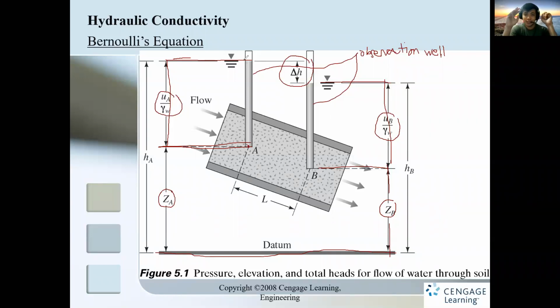That is one example of head added. If the pressure of the water is not enough to reach your tanks, that's the time you will need to add a pump, so that the water shoots up to your tanks. That is one way of transporting water from the lower point to the higher point. Head added is also used in computing the total head or the head difference.